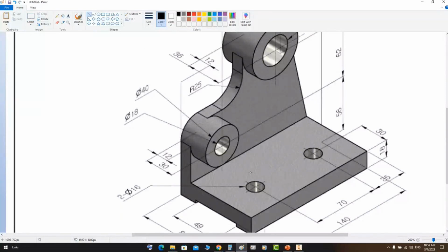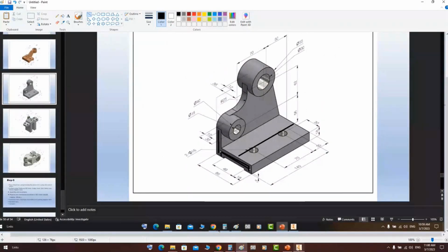we can make this cross section and make extrude for it, along here. So we will draw this cross section and give it an extrude. After that, we can select the back face and make this sketch, which is for this rib. Or we can make the section along here and there like that and make extrude. After that, make a cut here. So let's make the 2 ways to generate this part.